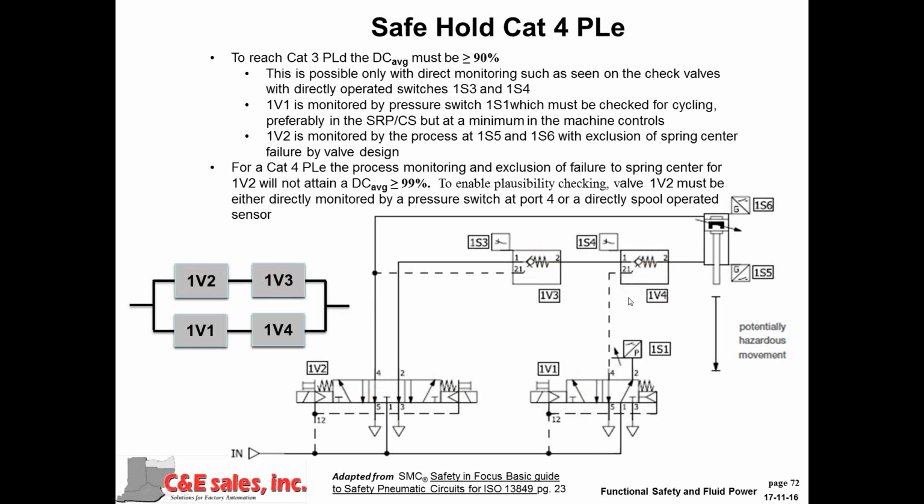Now, I can claim a category 3 PLd with this particular design because I can have a 90% probability of detecting a failure.